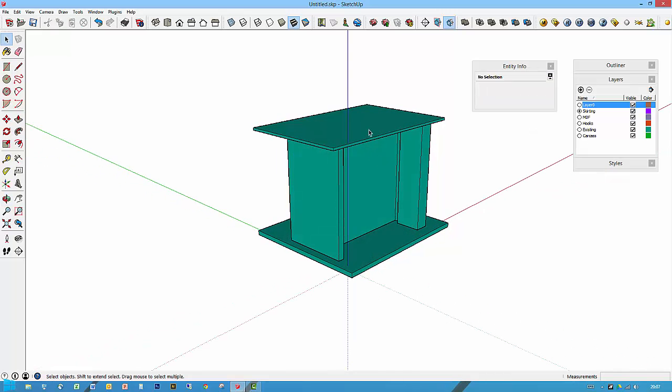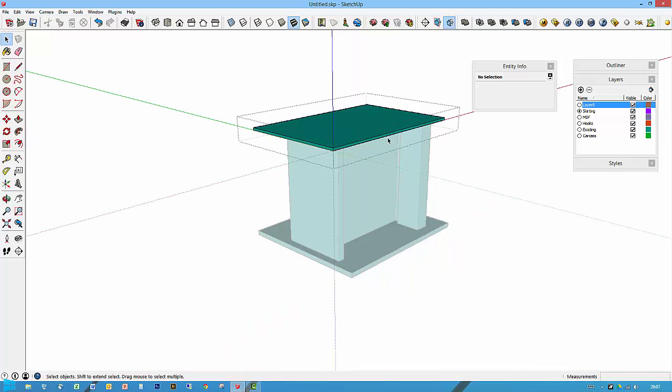What also happens is that as SketchUp does this, even though the group of objects is on that layer, inside this group, if I triple click, then everything is on layer 0. Now these aren't affected by the color by layer style, but it's always worthwhile, just in case, putting these onto the existing layer also.